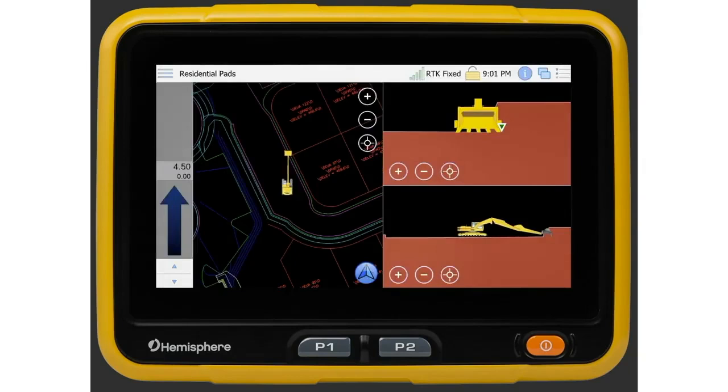Again, the above process is used for projects that have been engineered and have a CAD file or set of plans. The second way to control cut or fill within Grade Metrics is field design. This is useful when the customer will not be on an engineered site or the site will need a redesign done. We have included a few tools that will still allow the machine owner to use Grade Metrics in this case. You would not need to localize the site or have any of the files for this to work.